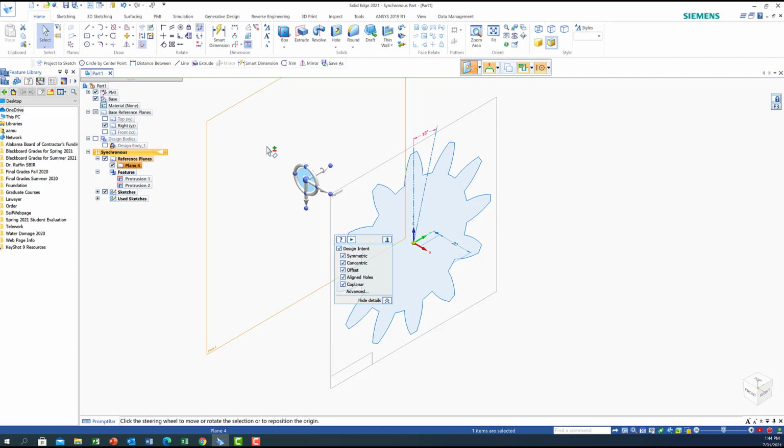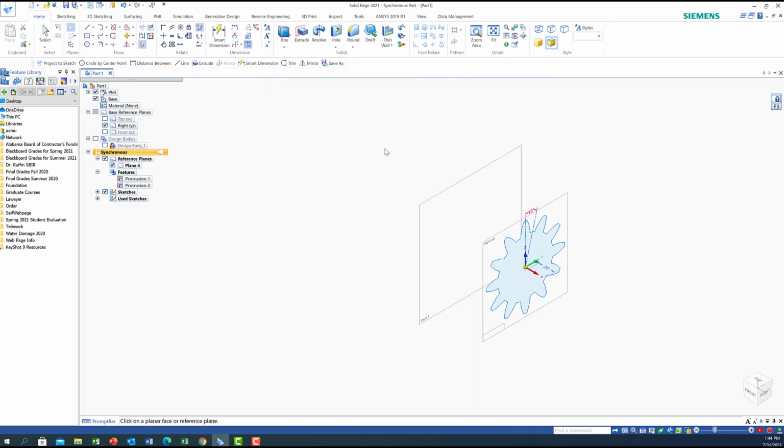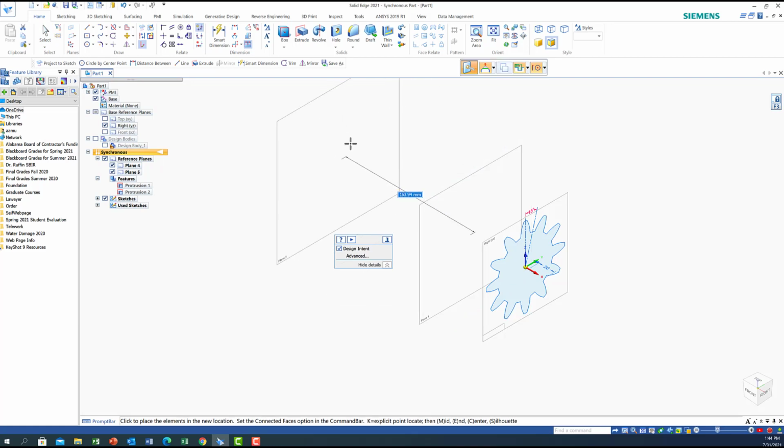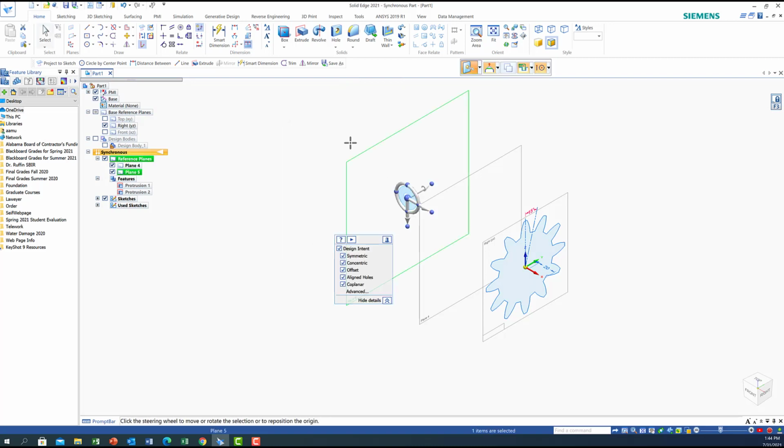Okay. Then after that, once I create a plane, I will do the same thing. Just now I'm gonna escape so I can have this one locked. Okay, so now, and then make another plane parallel to this plane, and I'm gonna go this direction. A distance how much? Say 80. Okay, I'm gonna put 80. And from this plane here, so escape. So now create another plane.